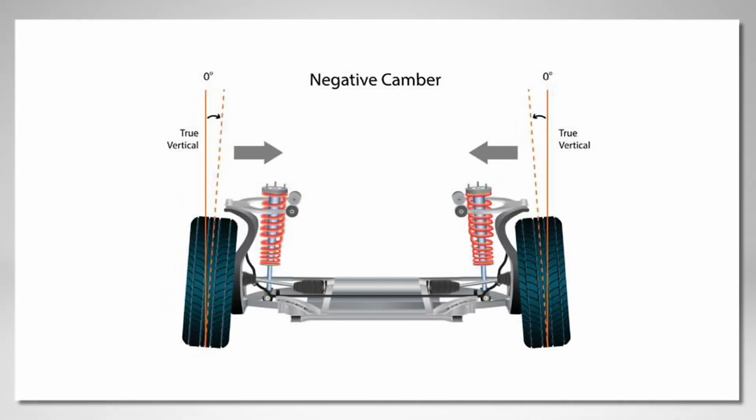For diagnosis of pulling complaints, remember camber values may be within specifications and still cause a complaint from excessive cross camber. The diagnostic rule is camber pulls positive, meaning the vehicle will pull in the direction of the wheel with the most positive camber value. Rear wheel camber is generally specified as negative on vehicles with independent rear suspension.